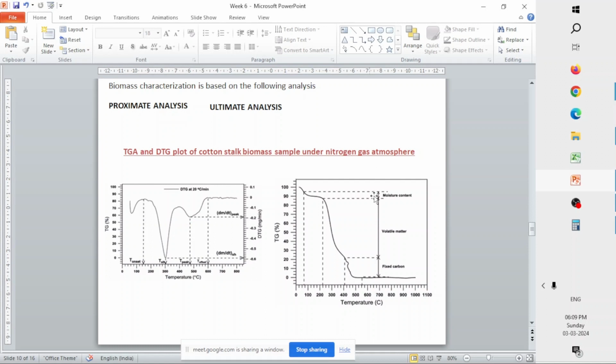So in those cases, if you see here, your graph falls with the temperature. That means the mass of your substance, the 5 or 15 mg that you loaded, is getting lost, is going down. The mass value is decreasing as we increase the temperature.